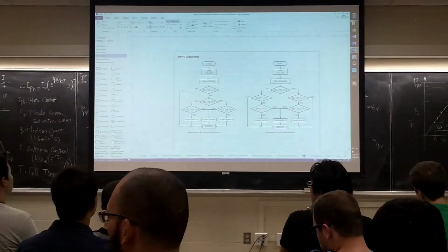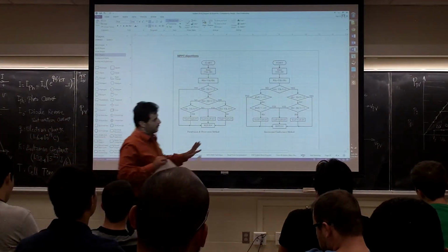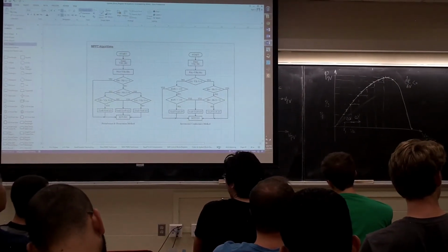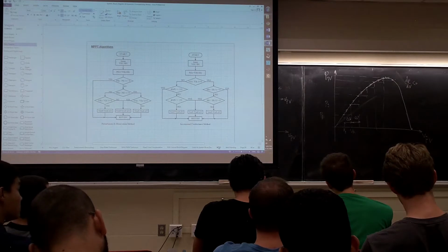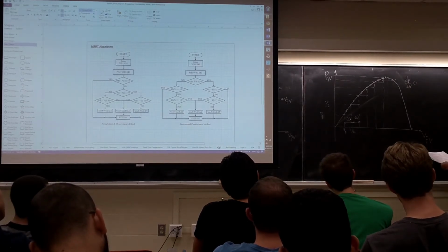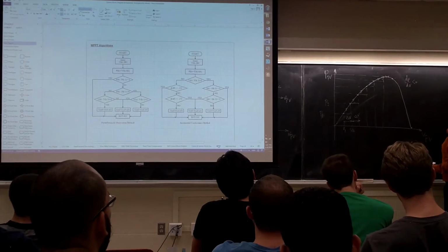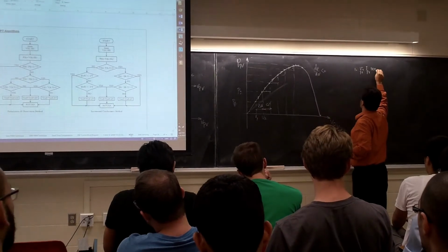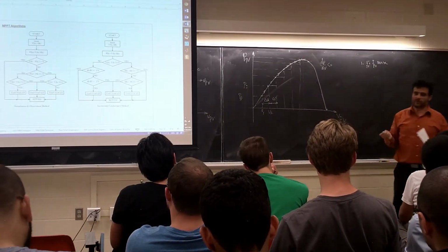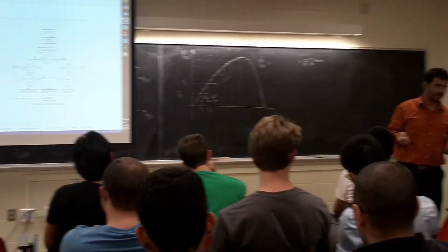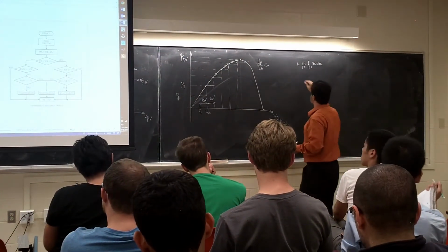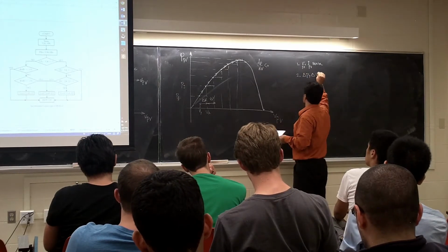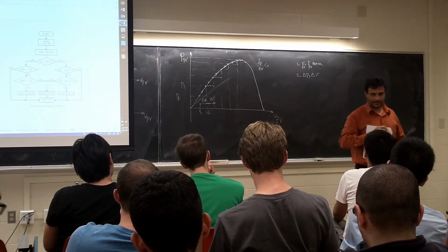Now, let's put the steps together for this one. What we are doing is changing the delta V. We add a step, we measure the delta P, and we figure out if delta P over delta V is positive or negative. So we start like this: we sense V and I, basically VPV and IPV. Sense means you're measuring the output voltage and current of the PV. Now the next one, you calculate delta P and delta V.